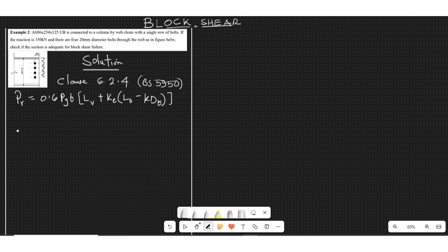The first thing we want to discuss here is the py. What is py? We can be quick to assume that our py would be anything. Say we want to assume that it is an S275 grade steel, and someone might be quick to assume that our py is supposed to be 275. Somebody can be quick to do this, but this would not be totally correct if you are assuming directly like this.